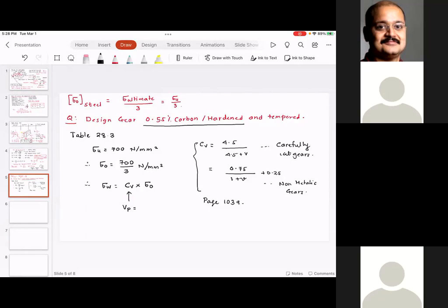When I say a composite gear, that means a gear made of non-metallic material like plastic, nylon, some type of exotic gear. Sometimes there could be a composite profile gear, where an involute profile is somehow modified. I have not given you any homework on non-metallic or composite gears. We are just following the complete involute or stub gears, so a standard gear profile.